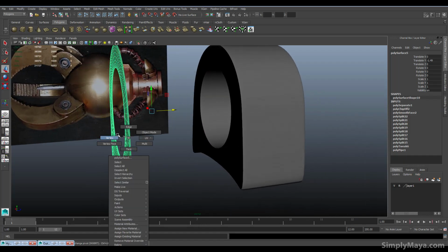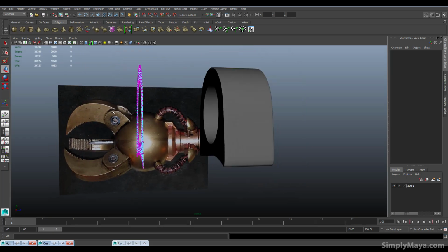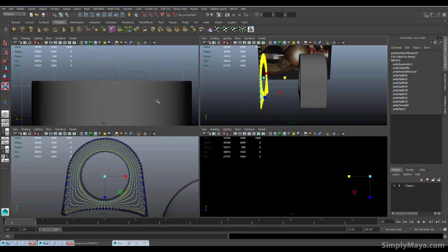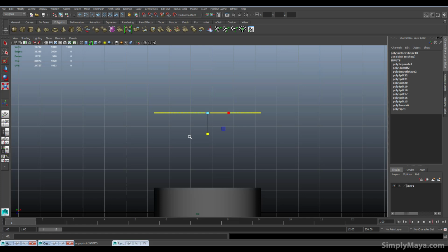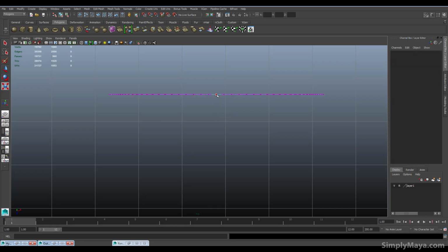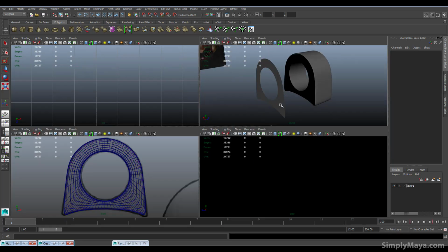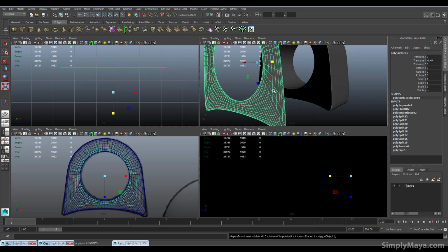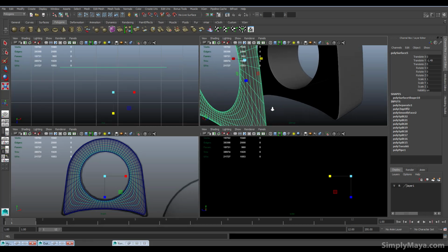Now we need to make sure it's flat, so I can do this by selecting the whole object or just selecting its vertices, selecting all the verts, and hitting R to scale and scaling them all so they are flat. Now easier to do this in this view probably. Okay, and I can see from this view that all those verts are flat and I can't actually scale in any more now, which means they're all perfectly in line with each other. Alright, so that does this. So now we've got our high-res geometry, and this is unsmoothed. Now this is a 1 on the keyboard, so this is actually unsmoothed.